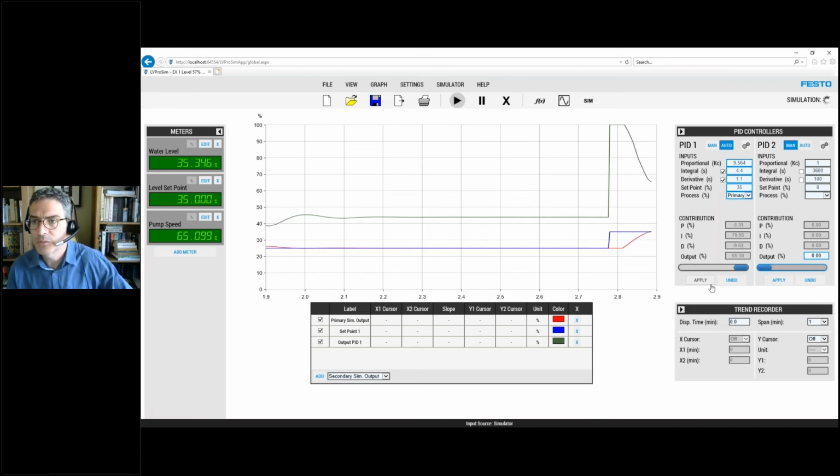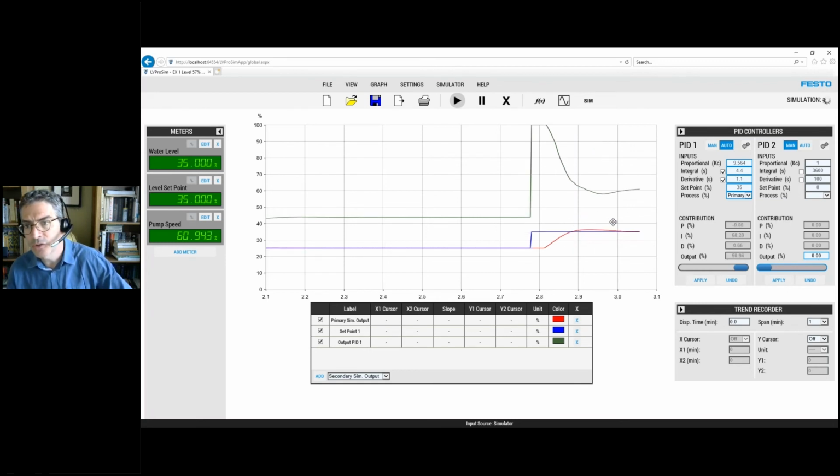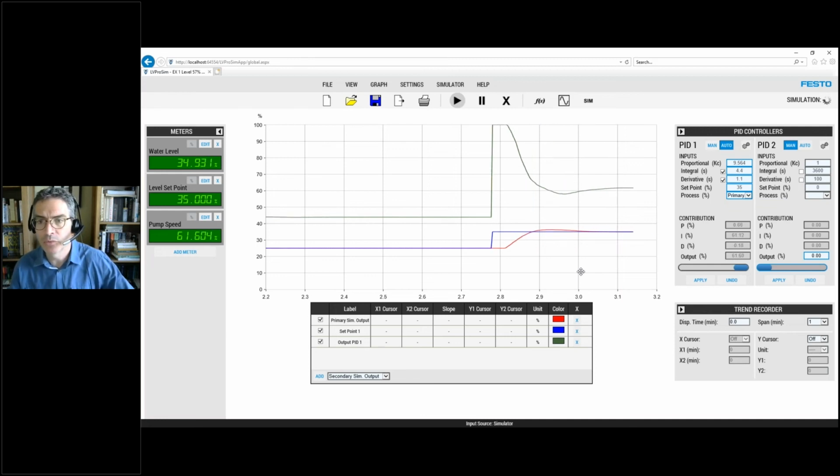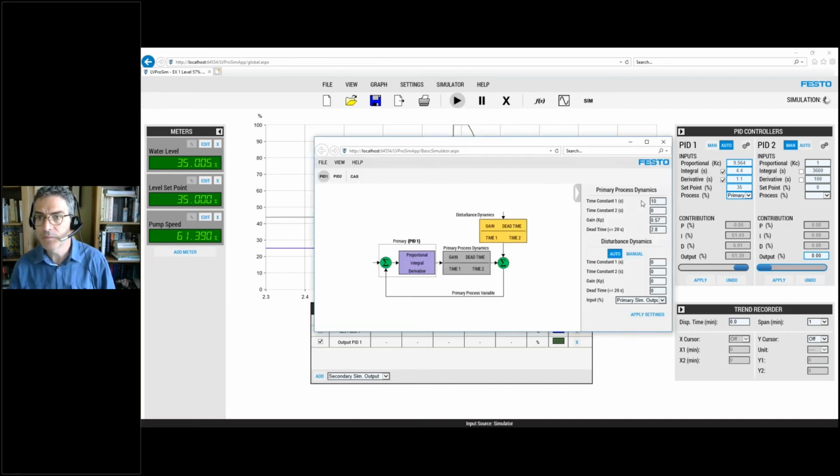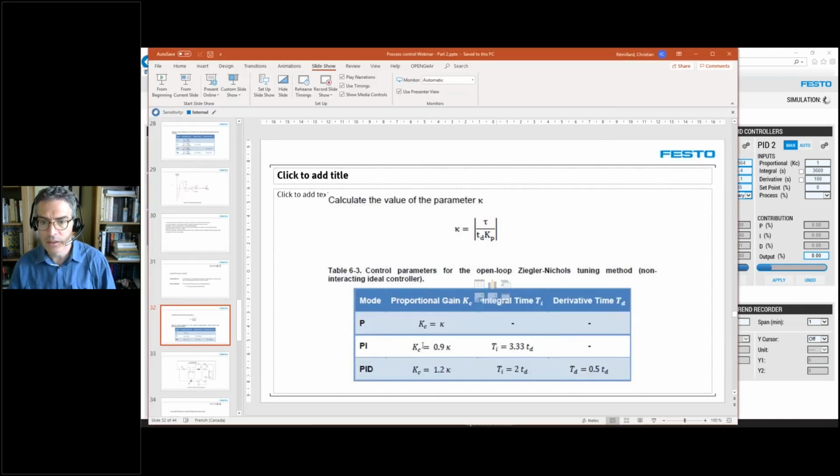So you will see that with these parameters, we get a really nice control, really quick, so no overshoot in this case. We get almost no overshoot and directly zooming in on the set point with no oscillation. So really fast response. So again, this was achieved simply by taking our three characteristics here and plugging them in the Ziegler-Nichols equations here. So that's a second way of achieving or finding the PID control.